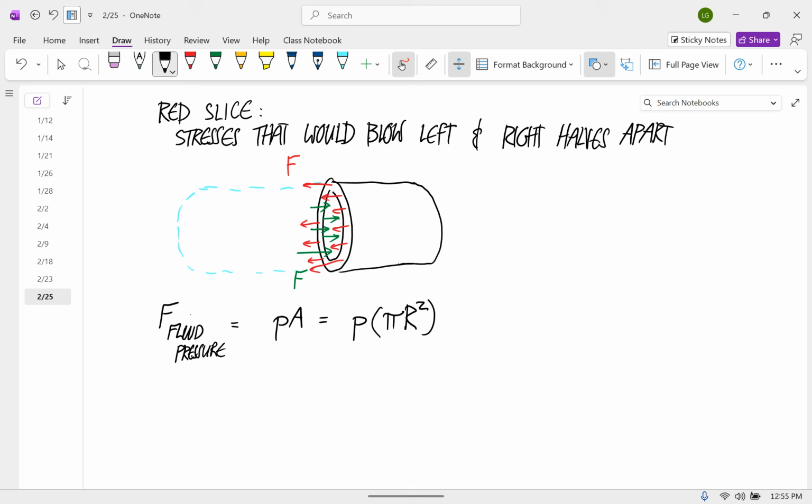And now the force applied to the metal is the normal stress times the area. Again, that area we can get by imagining unhooking this ring and stretching it out to make it a rectangle. So this is the thickness times the circumference, and then we still have that stress.